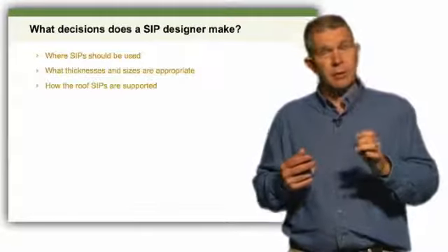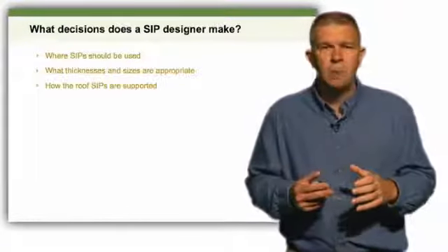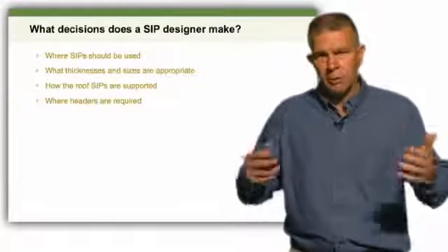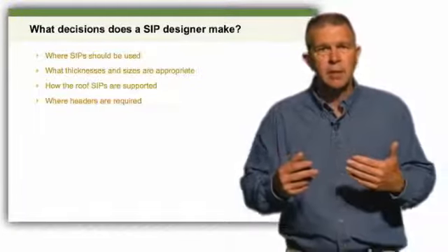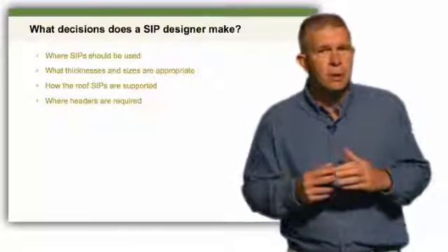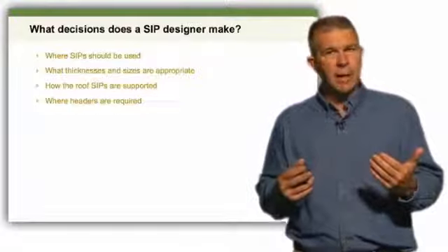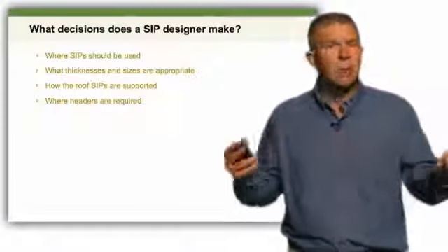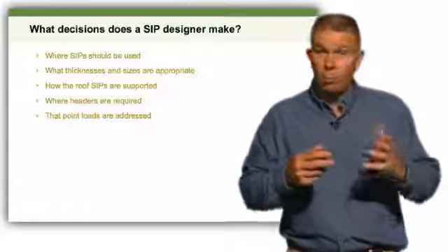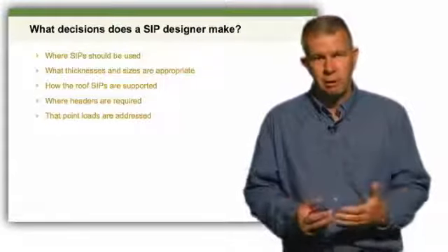Remember, if we talked about trusses, trusses do a great job at spreading all of this load to the front and the back wall or the side walls, depending upon the orientation of the truss. What the SIP panel package does is it incorporates more point loading because the panel has to span from either the eave to the ridge or gable to gable wall, and now we have a combination of either uniform or point loads coming down through the middle of our structure.